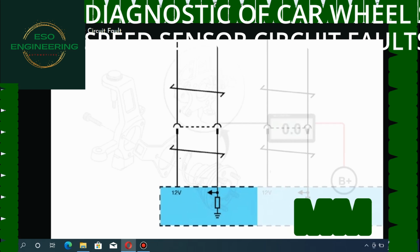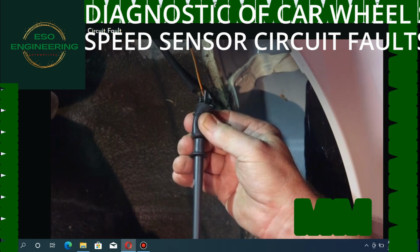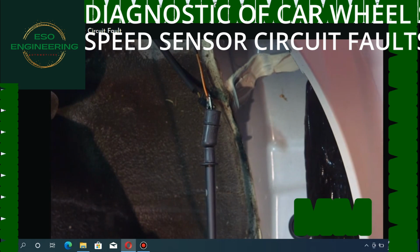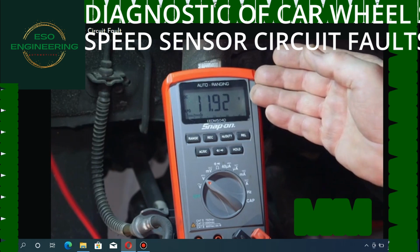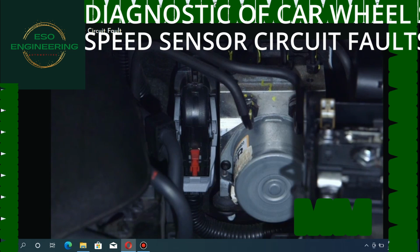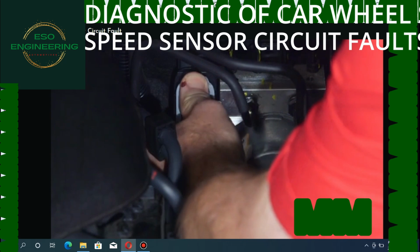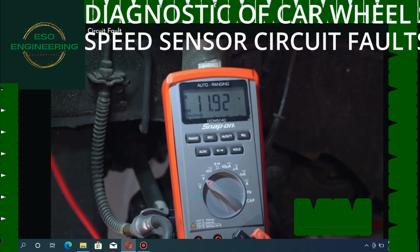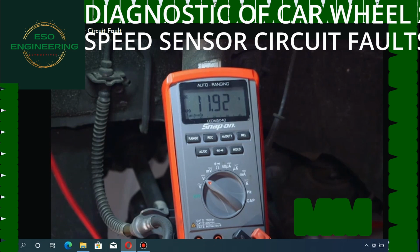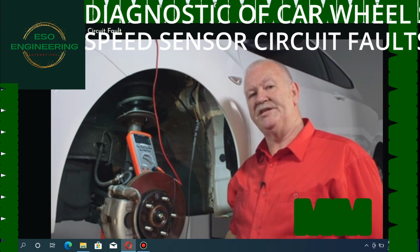There should be a ground on this wire from the pull-down resistor. To test this, connect the multimeter between the sensor connector signal terminal and battery positive. You should see close to battery voltage. This will indicate a ground on this circuit. To determine if it's a ground from the module or a short to ground, simply unplug the module and retest. If the voltage reading is still there, the ground must be coming from the wiring harness. If the reading is now gone, this means that the wiring is testing okay.